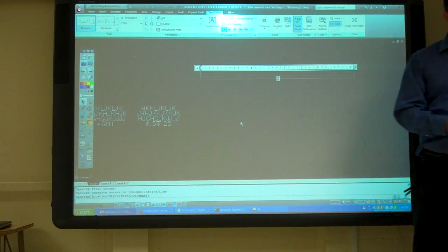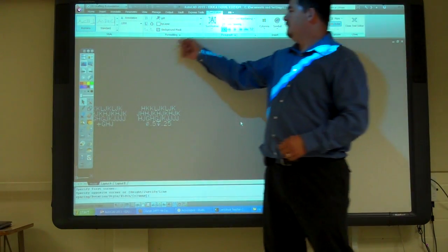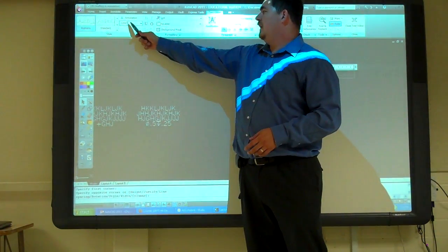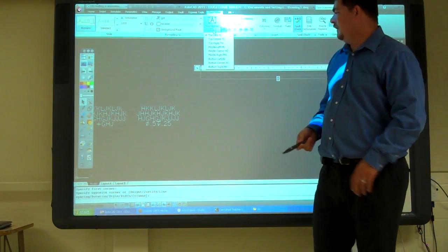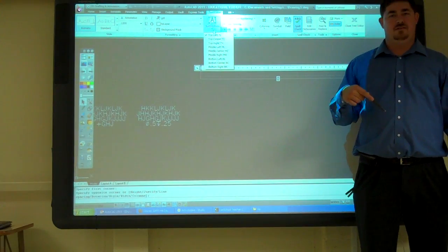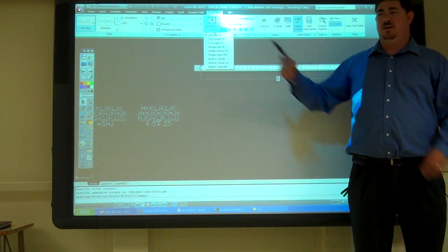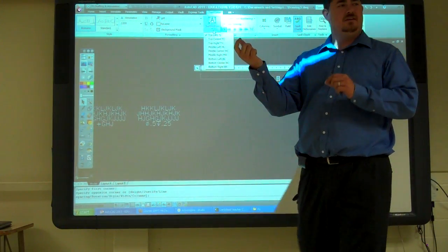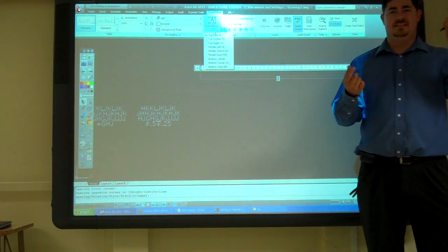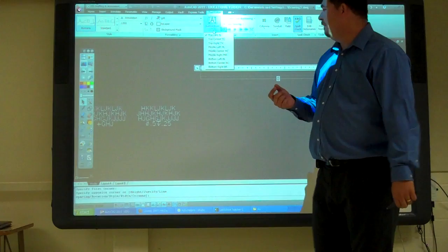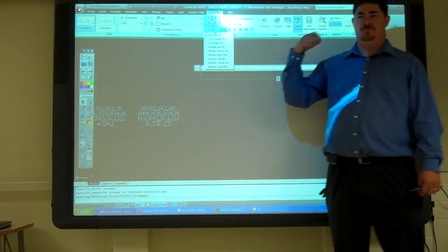It changed. Now it has a bunch of options for text. Things like a size, font, justification. So all those justifications I had before with DTEXT, I still have there. And single line text is called DTEXT. That's its name. It's not S-text, it's DTEXT. And then multi-line text is MTEXT.